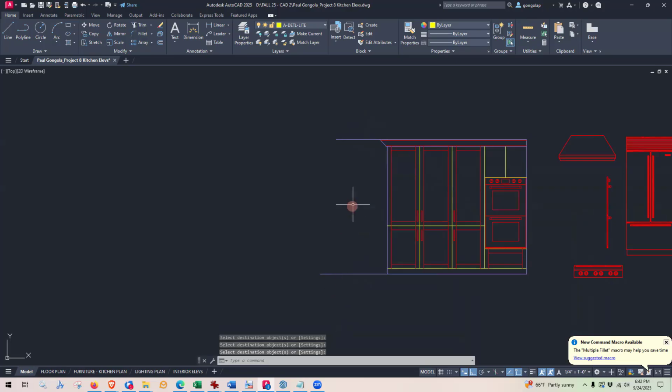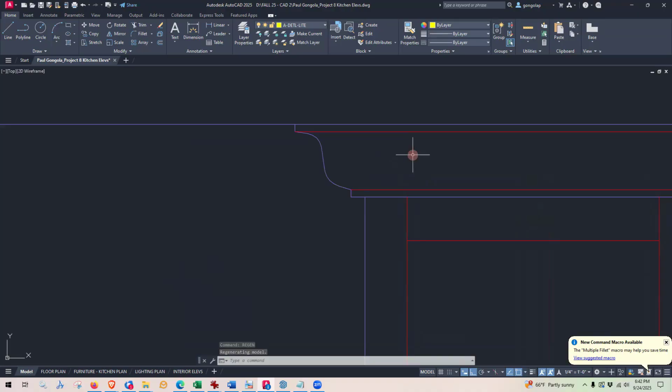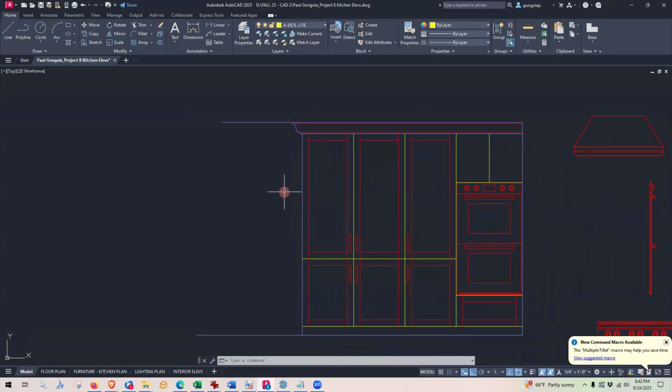And then I'm just going to do that break symbol here. AutoCAD is cutting corners here, so I'm going to regenerate my drawing. If I type REGEN, if you watch my crown molding, now it's curvy again. So AutoCAD tries to make life easy for itself. Circles and curved lines like this, it will often facet them in order to do less calculating. It's just trying to make its life easier. But I want to see that curve. So if you regen, you're telling AutoCAD, show the curves, and it will.